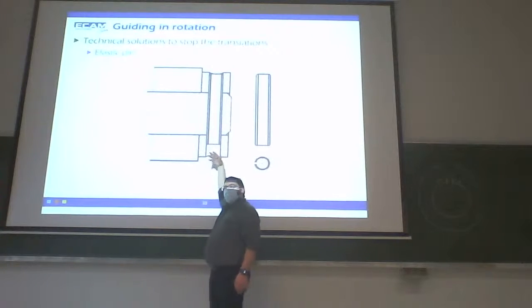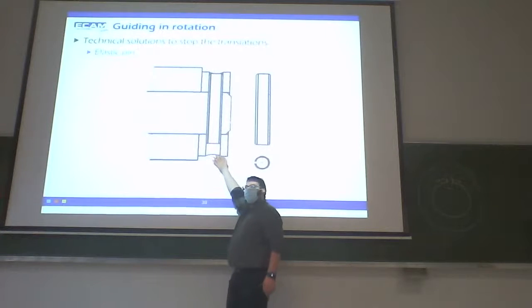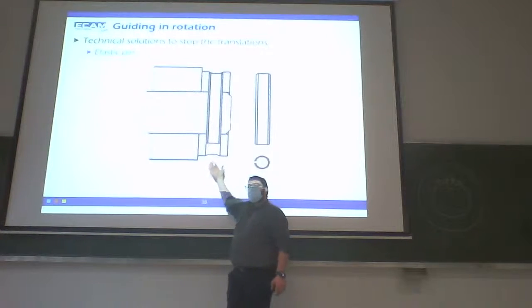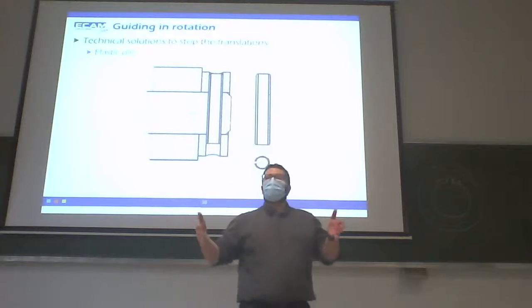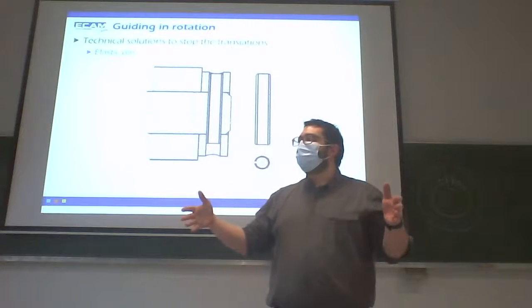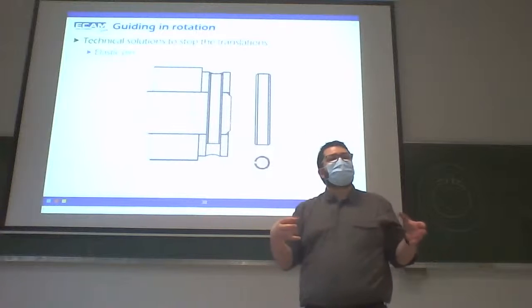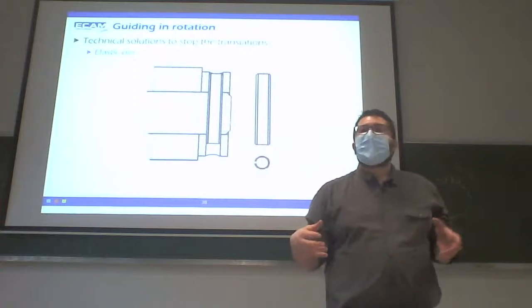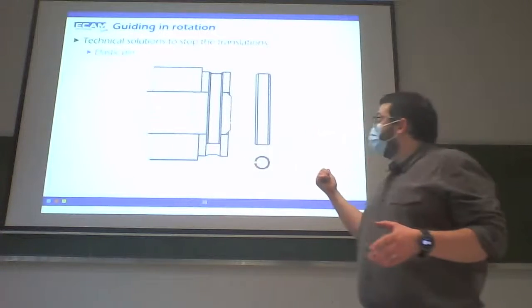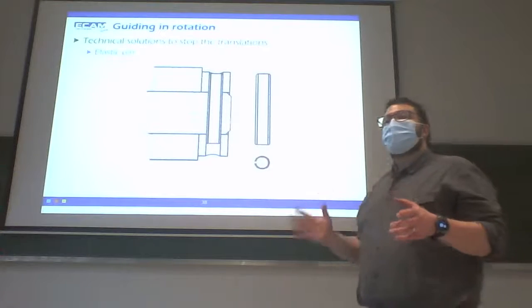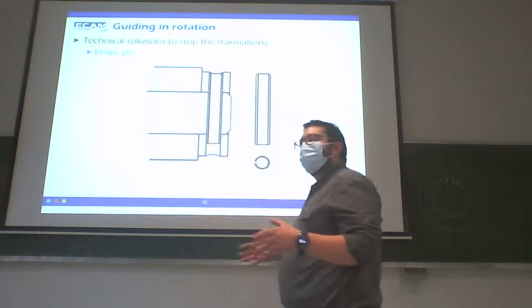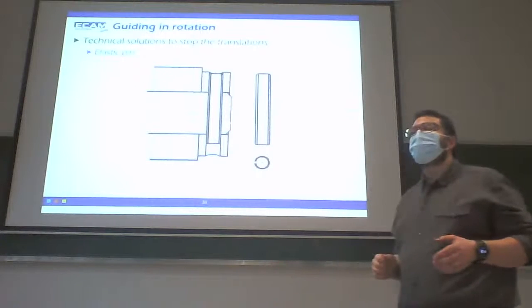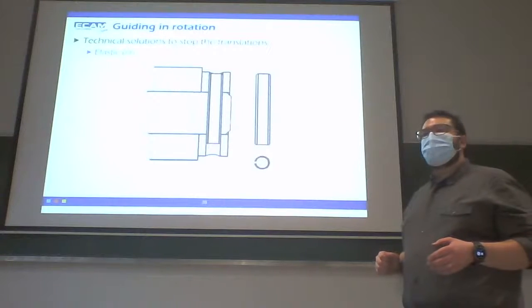It's almost like a shoulder, but here it's a demountable one, because it's not possible to put a shoulder on each side, because you can't assemble the part. So we add this solution to realize the complete joint, to realize the turning joint, the translation stop. Is it okay for you?